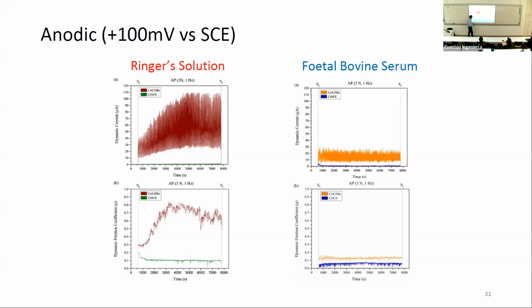Yes, because it's very resistant to tribocorrosion. Over here, we're seeing the friction coefficient. For the untreated, we're seeing quite a high friction coefficient, but for the chrome nitride, we're seeing consistently, both in Ringer's and in Ringer's plus bovine, a very low coefficient of friction. For the untreated tribopair, we can see that the addition of proteins is very beneficial to lower the coefficient of friction. It's showing that these proteins form some layer which is very lubricious on the surface.